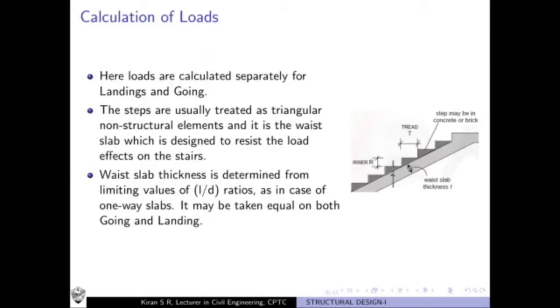what you should do next, you have to calculate the loads. Why? Because you need to determine the moment to be resisted by the slab or the staircase. Okay, so for which you need to calculate the loads. And how are you going to do it? The loads are calculated separately for landings and going. The landings and going, you determine the loads separately.